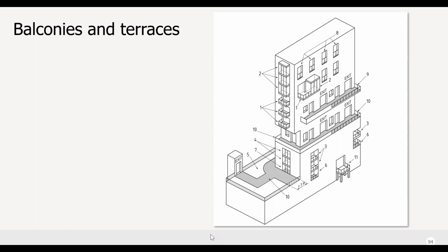An understanding of how rainwater affects a balcony and its surrounds is essential for good design, and the following should be taken into account. Incident rain, there's the influence of balconies above, flanking walls, imperforate guardings, uplift and eddy-borne rain. And for small balconies, this usually means that precipitation is not a problem.